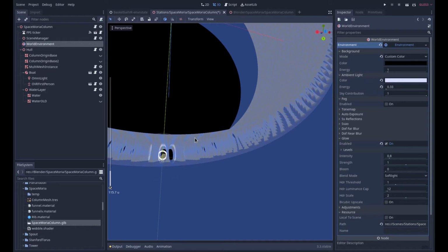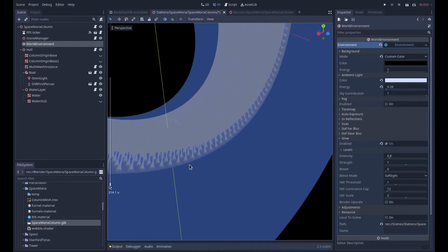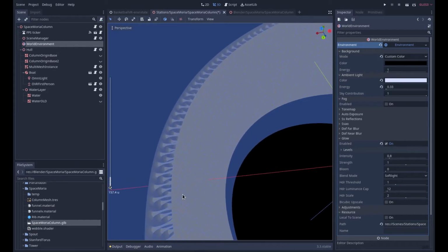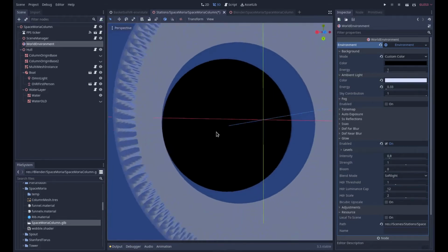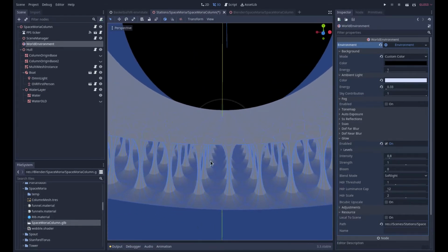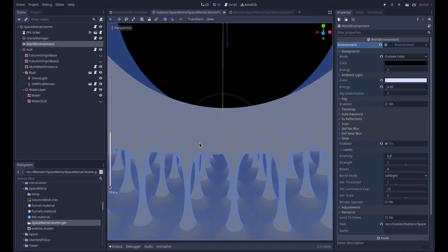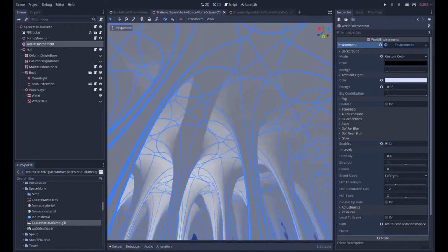And then the shader is taking that and warping the edges so that that rectangular object fits around a circular array. It's repeating once in one direction, and then repeating in the other direction. And as you can see, there are hundreds and hundreds of these things, and it still renders pretty quickly. If this were not using the shader to bend things around, it would overlap too much on the top because the bottom would be bigger than the top. To fit in this cylindrical environment, it's got to be squished in at the top, which the shader does.